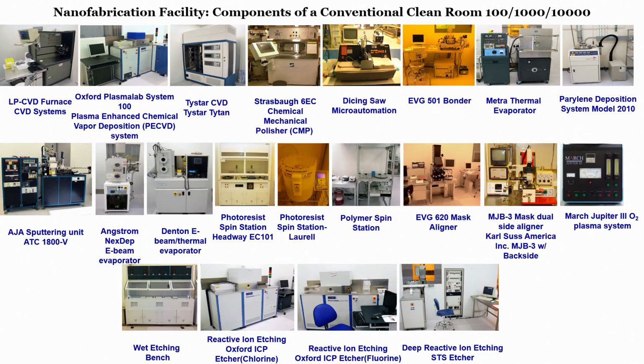However, every time a system has some positive points, there are some limitations as well. So, what are the limitations of PECVD over LP-CVD? This is also chemical vapor deposition, it is just plasma enhanced, while that is low pressure. The thermal oxidation gives a better quality of film compared to PECVD. So, if you require the film quality to be extremely good, then you have to rely on thermal oxidation. For devices such as micro electromechanical systems based sensors, you can use LP-CVD as an intermediate layer or as an insulating layer between two metals, or a metal and a semiconductor. I will talk about that at some point.